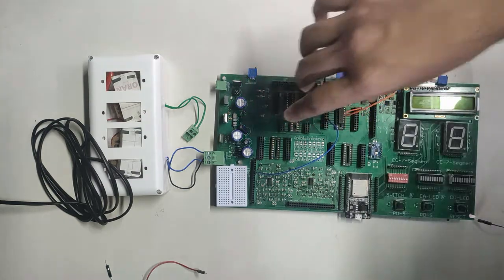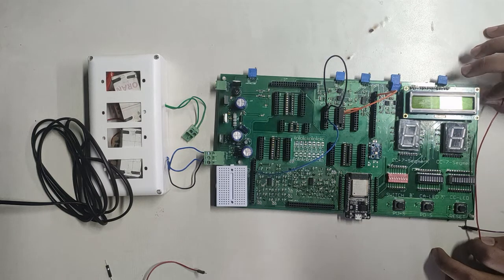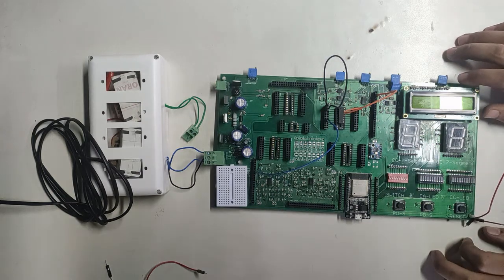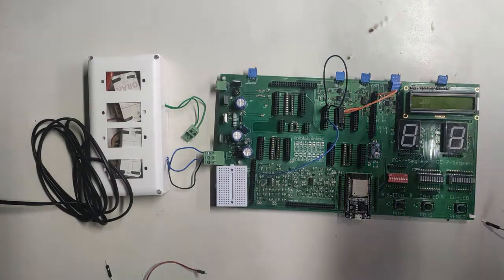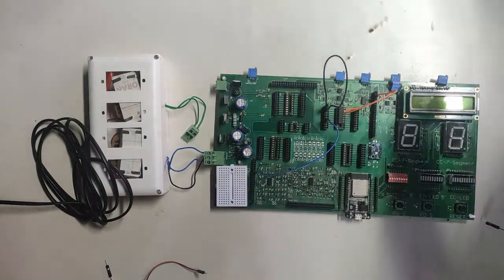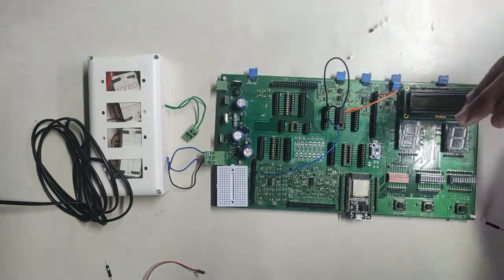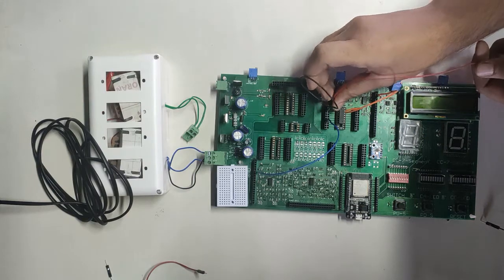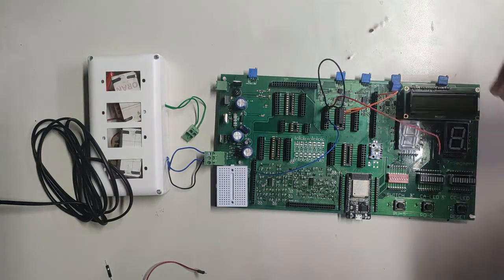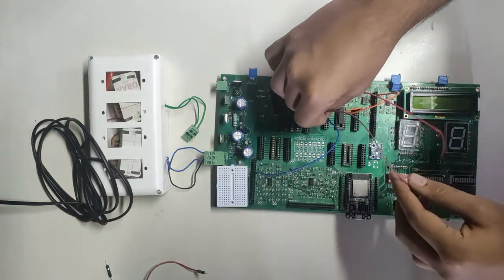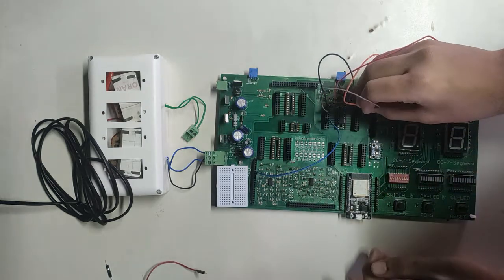When you see the circuit, you can see that both the inputs are shorted and then given to two separate NAND gates, and the output of those NAND gates is again given to another NAND gate, which performs the OR operation. So here at first we have shorted the first NAND gate, whose input is A, which can be given through this red wire. And the output of the first NAND gate is given to the third NAND gate.